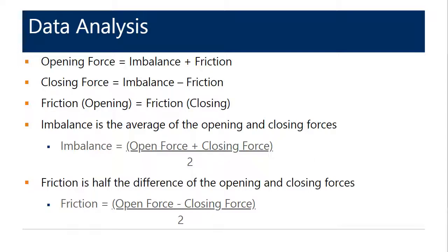Not necessarily. While a light imbalance condition could contribute to seating problems on a vertical lift, there are other factors involved, including ensuring that the machinery is properly indexed, ensuring that the live load supports are at the correct elevations, and ensuring that the control system is applying and maintaining sufficient seating torque in accordance with AASHTO recommendations. Strain gauge testing is the only way to positively, quantifiably establish the actual bridge balance, and that a sustained seating torque is retained by the machinery.